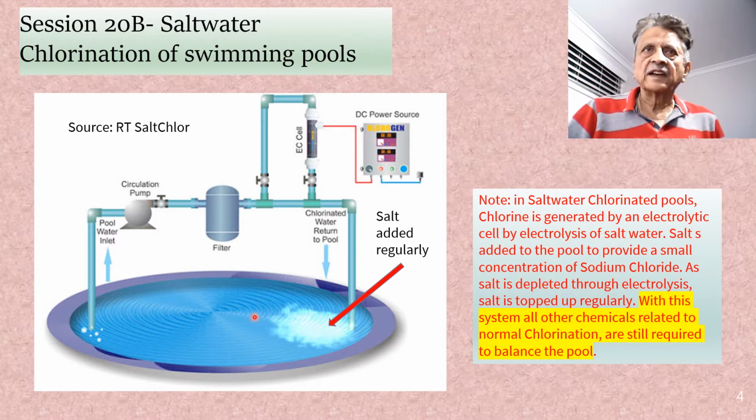As we have explained earlier, progressively the depletion of chlorine will cause the water to be alkaline, and it is necessary to ensure by frequent checking of the pH that it is maintained below 7.8, preferably at 7.2 to 7.3, and this is by addition of hydrochloric acid. So that will restore the pH as well as some chloride.